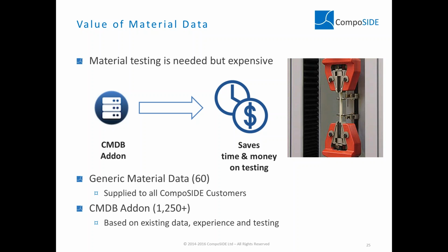single material data testing. And those are materials that can be used across a number of different industries by just applying your industrial partial safety factors and your design allowables. So in that case, when you think about it, what you're doing is that you're starting by selecting the materials, and it's only later on in the process that you're actually starting to validate those assumptions through actual testing.